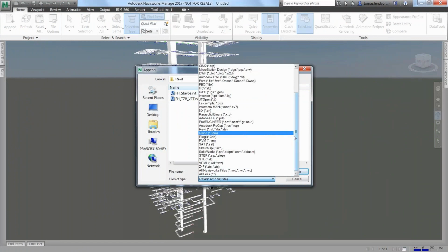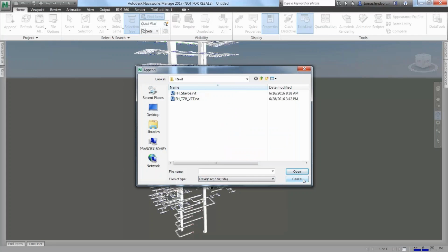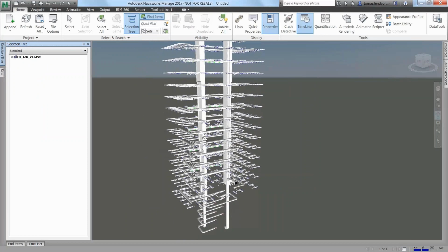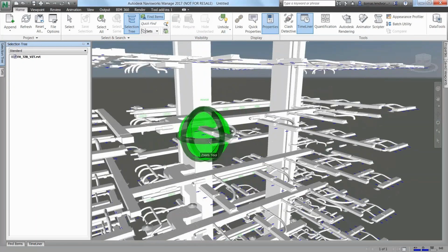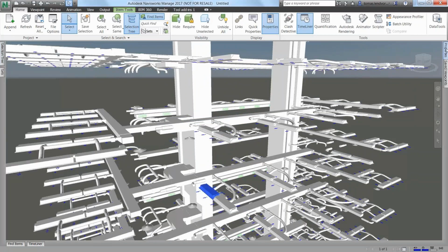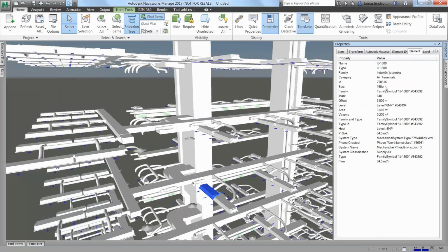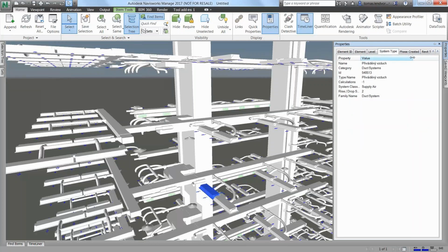And now let's have a look. I'm a supervisor, and I have Autodesk Navisworks. And now you can see that within Navisworks we can also upload a lot of different types. So what happened is I received an invitation to the BIM System team project. I downloaded on my computer the Navisworks model or Revit model which has been shared to me. And now I aggregated it to Navisworks, and you can see that Navisworks is also allowing me to see all properties of each and every element.